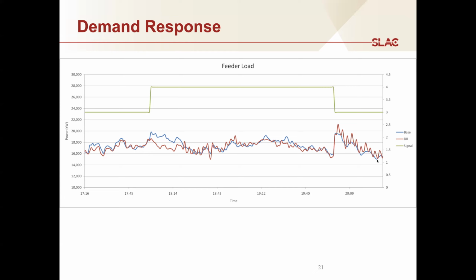So there's what's called synchronized states. And so this oscillation will persist for a time until that state synchronization in the thermostats dissipates. And in the meantime, what you see is that the load rebounded, right? There's more load than there would have been in the base load case. And so, yeah, essentially this is a kind of no free lunch principle.